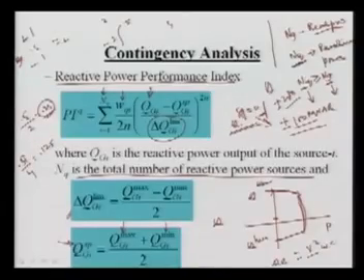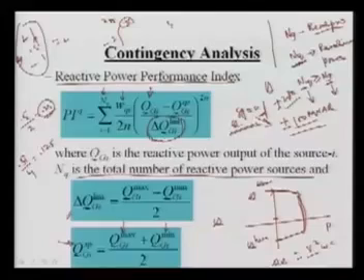So this value we can say is very critical. Why? Because you can see the range: here we have only 0.5 margin to the limit, but here with 0.5 we have more margin. So this case is less critical than the other. This gives basically the relative margin you are having. So this is a very important factor. If you are not using it, then you cannot tell the difference, and both will be equal. So it shows that the Q limit is divided to take the importance of that range into account, and that range is defined by the change in the QGi limit, equal to QGi max minus QGi min divided by 2. We are just taking the average here.